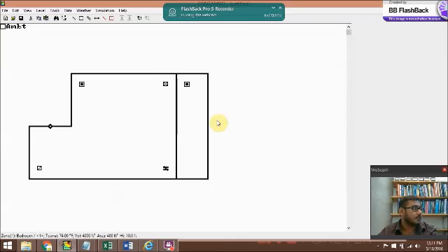So your airflow would be determined based on that. If you're modeling the room and the hallway, right now you don't have a door to the hallway, so there's no connection. But if you added that door to the hallway, it would have a natural leak underneath it, and it doesn't matter that the return for the house is a room away. It would know to allow air to go out underneath that door as well as through the window. Yes, you can even put a schedule for opening the door, so it's not just through leakages.